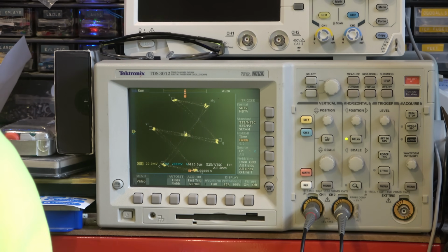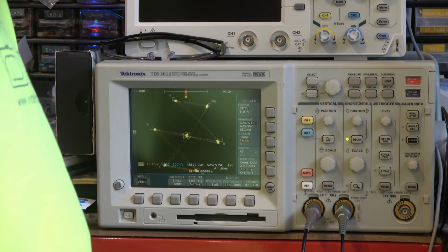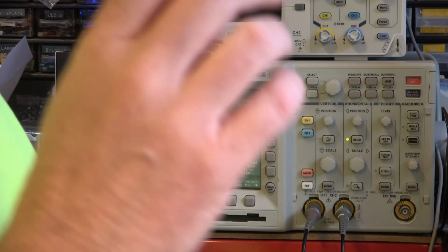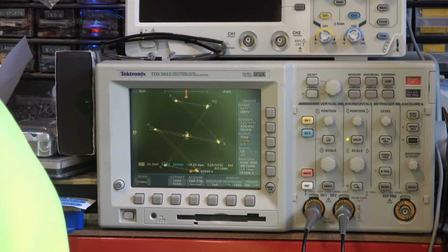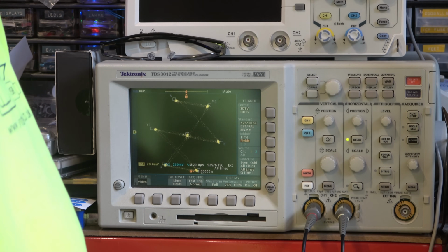Did we think that maybe that's something to do with timing? Phase, chroma phase. So if I adjust chroma phase, yeah, they come in a little bit with a chroma phase adjustment. So that's sort of saying that the dub cable connection is introducing a small chroma phase error. Maybe that is what this is telling us, and it's not supposed to do that, but it could just be a limitation of the system.